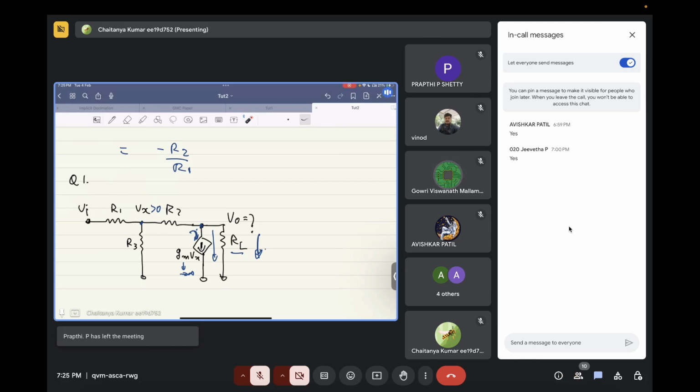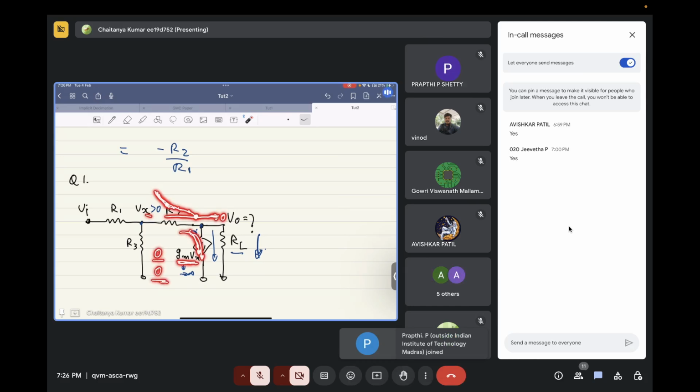So if, let's say, Vx was some quantity greater than zero and infinite current started flowing through this, Vx will start going towards minus infinity. Now, as Vx is going towards minus infinity, the current that this guy is taking out depends on Vx, so it will try to cross the zero axis, right? So this current starts reducing and reducing, and the moment it comes to zero, this basically becomes a zero by zero kind of term, so it becomes a finite value.